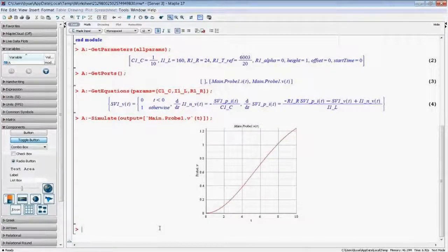And then one of the most useful commands is get compiled proc. That compiles the model into a procedure, and that becomes very useful when we're interested in doing analysis on the model and we want to run the model over and over again, making only changes in the parameters. If we do it through get compiled proc, we only compile the model once, and then we only integrate every single time, as opposed to compiling and integrating every single time. So it's much more computationally efficient.